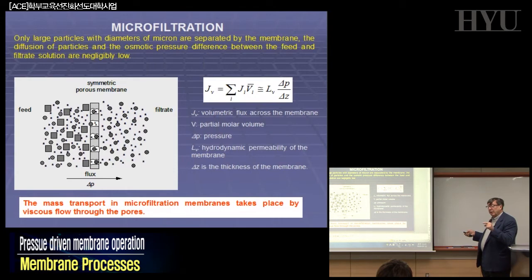Today, if some of you has to design membrane distillation, for example, new membrane distillation, you will realize that this system is a little bit more complicated, and this relationship is no more valid. You have to increase the thickness of your membranes compared to microfiltration. Sometimes the membranes are the same, but when you operate porous microfiltration membranes in polypropylene and PVDF, in microfiltration, the thickness has to be the lowest possible.